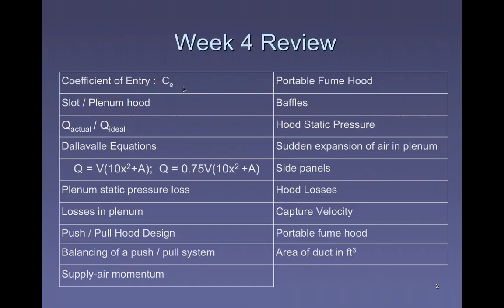So the more velocity that you have and the lower the static pressure is, that's a bigger number than if the static pressure were high and the velocity pressure was small, right? So if you have to suck real hard to get very little velocity or velocity pressure, that's a less efficient hood, and that number, when you take the square root of that fraction, is going to be a smaller number.